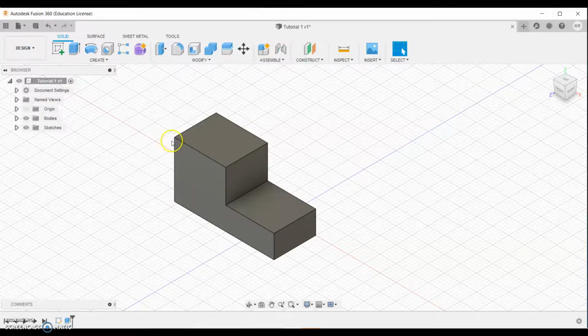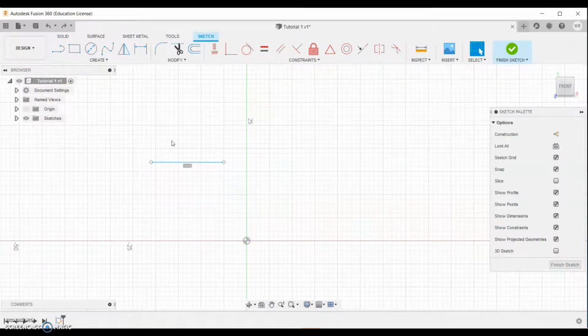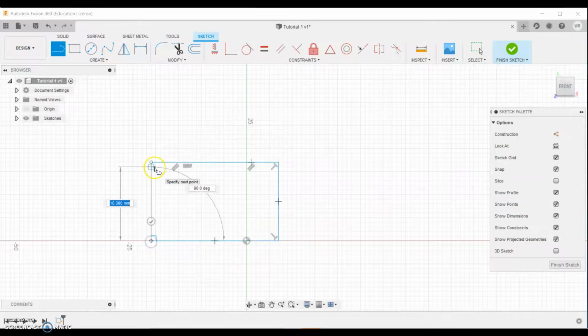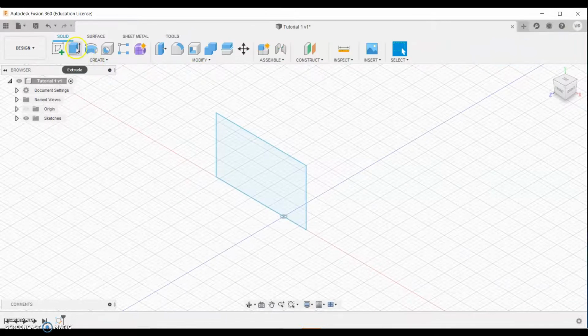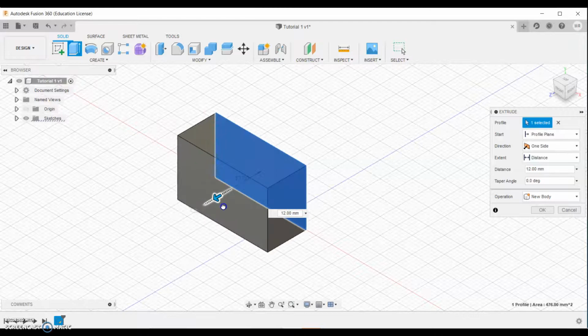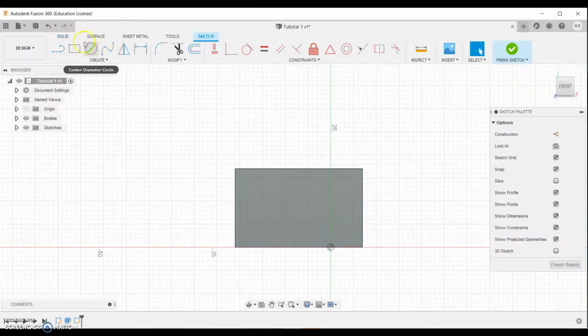All right. So if we go back and I wanted to redo this object but use subtractive, okay, I would instead create my box like so, finish the sketch, extrude it, enter, and then I would do a new sketch on one of the surfaces like so.